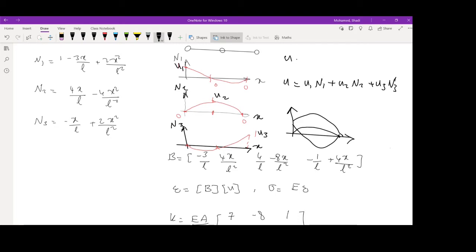So if you look into the first equation, we started from the parabola equation. It was ax squared plus bx plus c. And assuming that a goes to 0, then you have the line equation left, and you can represent any line. So you can basically represent anything that is second order or lower, and you can represent it exactly. So this is what you can do with the quadratic elements. Now, a parabola is a second order function, so you can recover it exactly. And this is why you basically use these quadratic functions. And of course, you can also use them to recover a line.